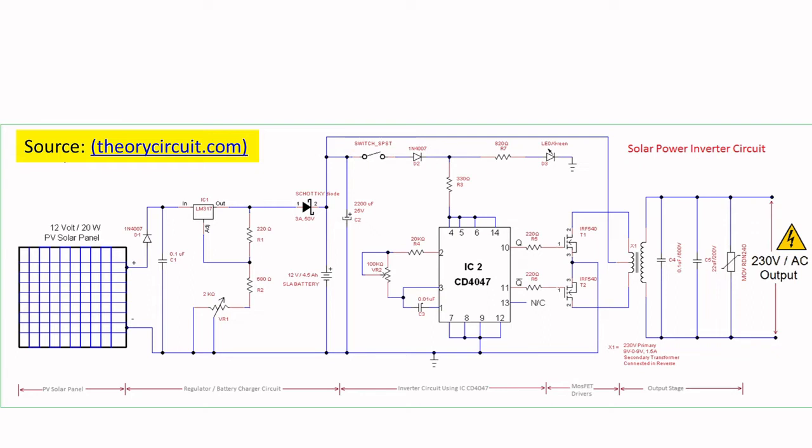When you are designing in LTSpice, the CD4047 and this LM317 will not be available in the parent directory of LTSpice. So you can do either of two things. One is you can download them from the net and add them in the parent directory. Otherwise, we can add them in the working folder. I'll be asking you to use the second method, and I'll show the same here.